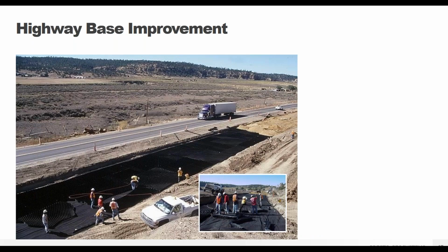So the GeoWeb system can be used under all types of roadways, from private drives to full service highways. So this was a project for the New Mexico State Highway and Transportation Department. Unable to proceed on a timely basis using any sort of conventional alternatives, such as super deep excavation with really thick base layers, or even using chemical stabilizers, the DOT turned to the GeoWeb system, and a local sand was able to be used as the infill material underneath an asphalt pavement.